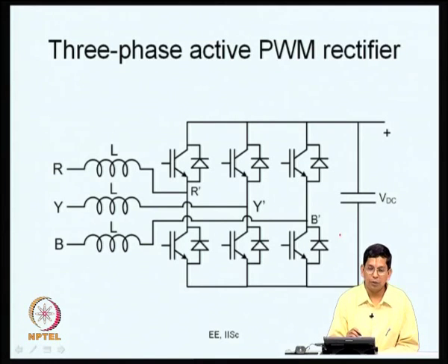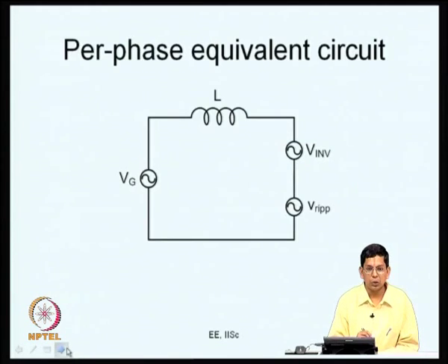In fact, if you are looking for what is called distributed generation, on the DC side you can have a DC source such as photovoltaics, or you can have a converter which rectifies the power available in some other alternate source. And that power can be pumped into the mains using this converter. So, it can be either single phase or 3 phase.